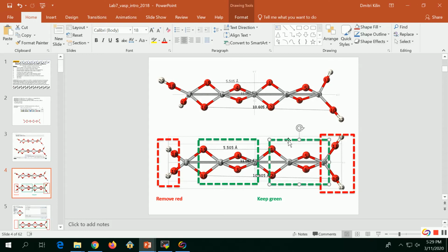Yes? So if I do not put the vacuum there and then do the minimization? No, it will not fix it. You cannot do it. There are special commands to adjust the size of the cell, but they will fix only small corrections. If you start from a predominantly jammed, wrong size of the cell, nothing will help you.